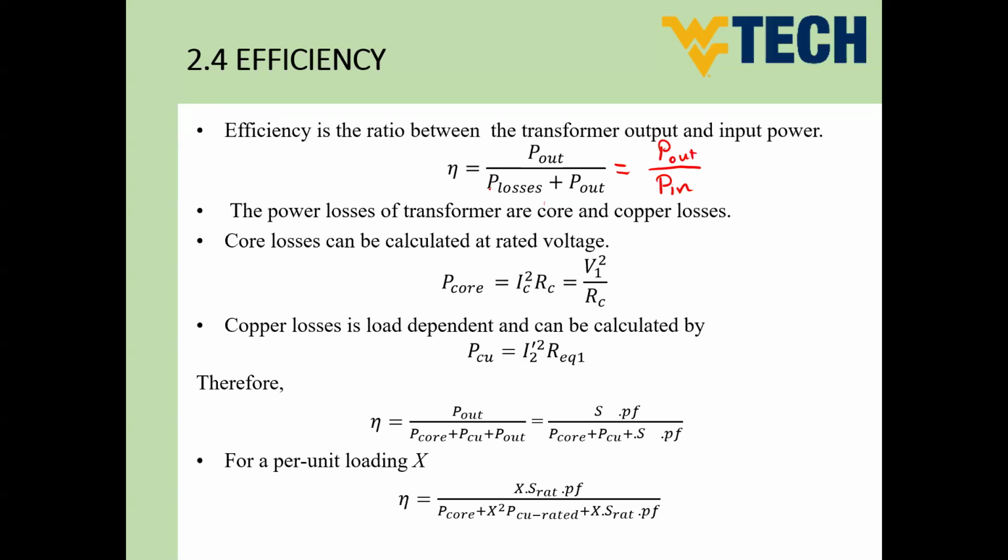Here specifically for the transformer, in order to do that, we need to have lower values of resistors. But at the same time, you have some other constraints, like how much inductance you should have, what the coupling coefficient is, and so on. During design of a transformer, we also consider some mechanical aspects in terms of the core frame and the window of the winding and so on. So we have so many parameters.